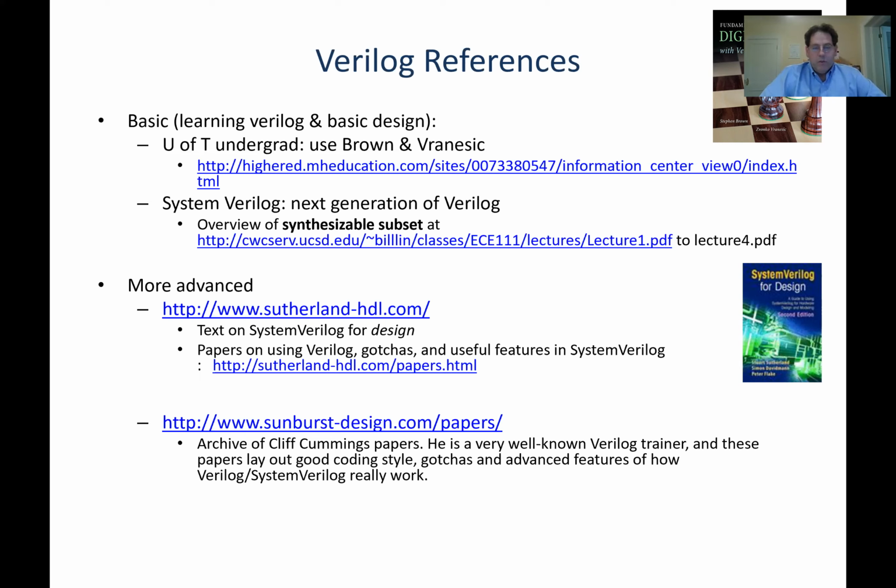System Verilog is really the next generation of Verilog. So they give it a new name, but it basically just adds some additional features to Verilog. System Verilog has a lot of features for simulation. So those are basically for writing test benches. For both Lab 1 and Lab 2, we wrote the test benches for you, so you don't have to write them. So the part you care about is what's called the synthesizable subset. So the part of the language that actually describes hardware that a tool like Quartus, or if you're using Xilinx Vivado, can actually turn into hardware.